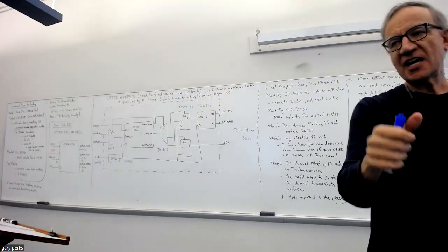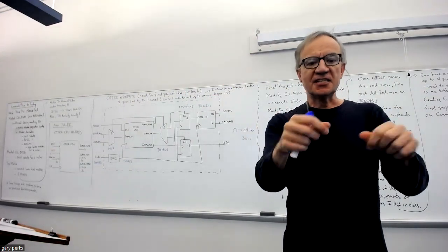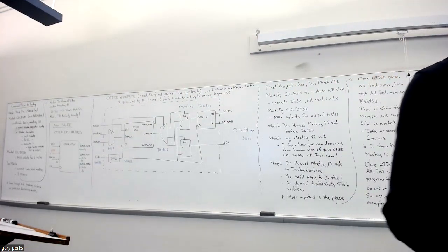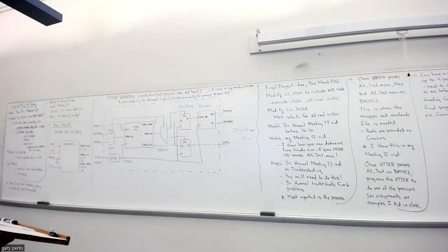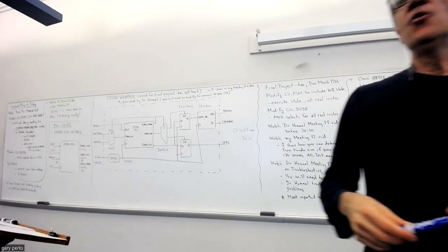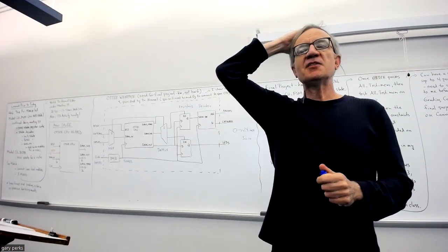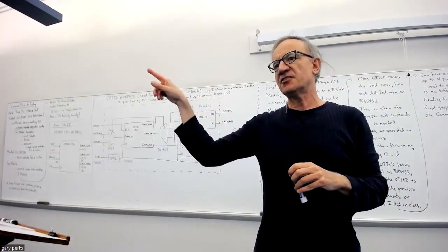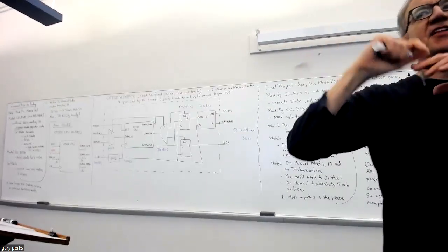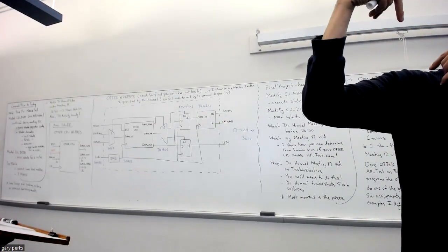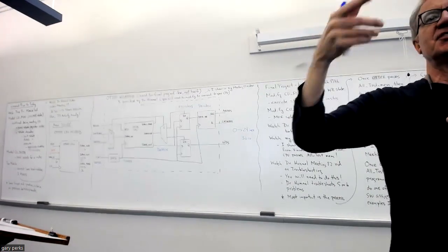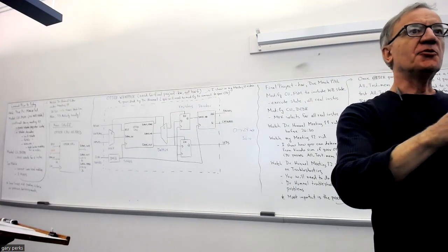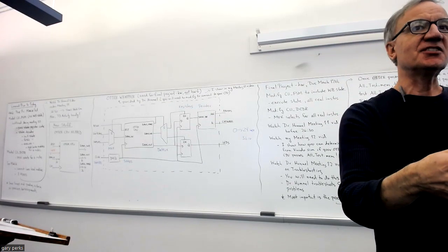And on the input side, if you've got switches, you'll need a delay to give the user time to change the switches. Just like in some of the software assignments, you were reading data from the switches. Well, you would still have that, but you would also need to include some sort of delay so that after one set of data is inputted, there is enough time for you to change the switches.